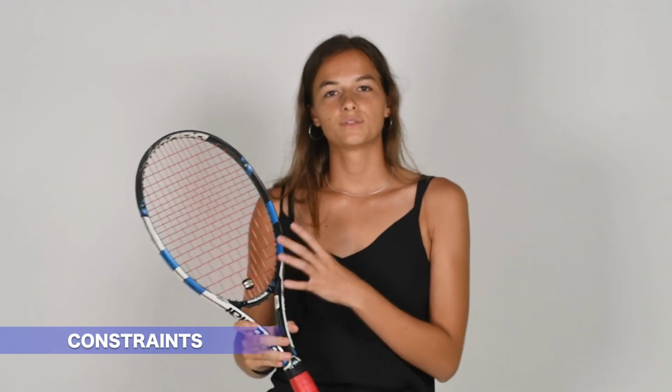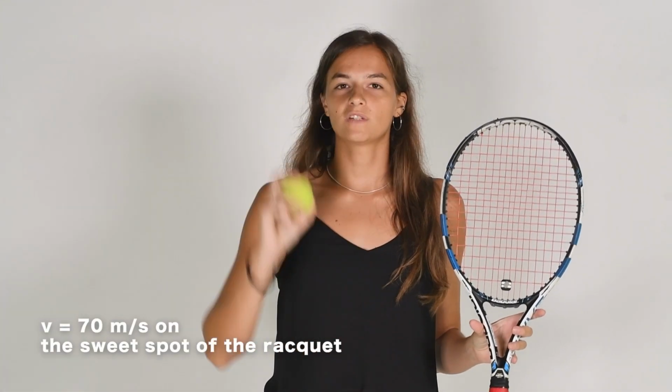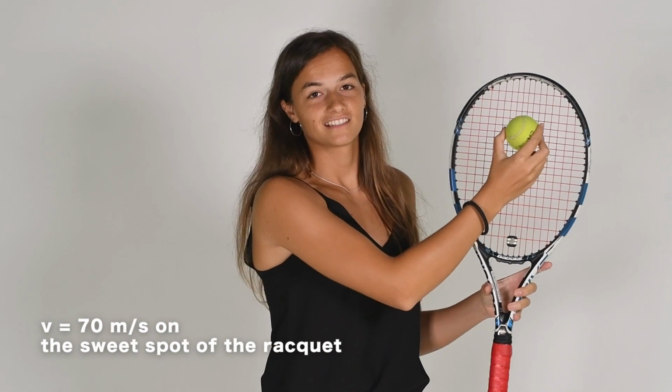Next, we have the constraints. For the simulation of the racket's efforts, we fixed its structure by the handle, blocking everything on the X, Y, and Z axis. To hypothesize the forces on the racket, we have used a critical case, where the ball impacts at 70 meters per second on the sweet spot, which is located here, and which is the point of minimum